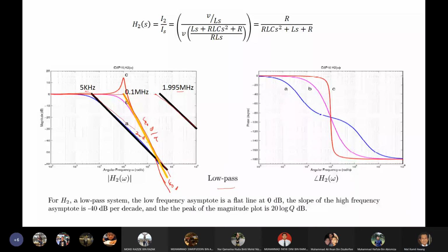It's difficult for me to draw, so I use the same curve. That is represented by this peak. So it's still the same in terms of your Bode plot. You have flat until it hits 0.0977. Since you have 2 poles at the exact location, it goes down 40 dB per decade.